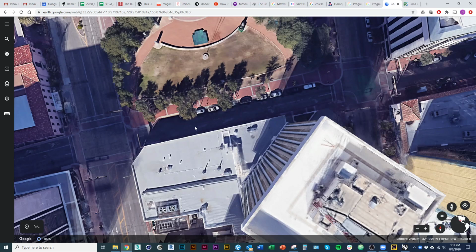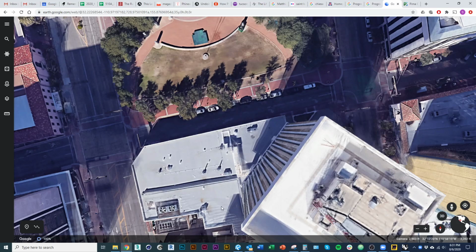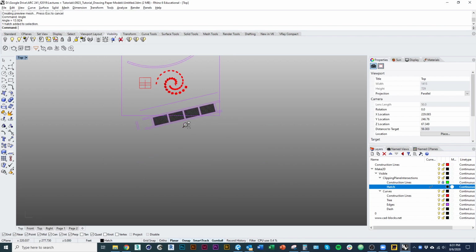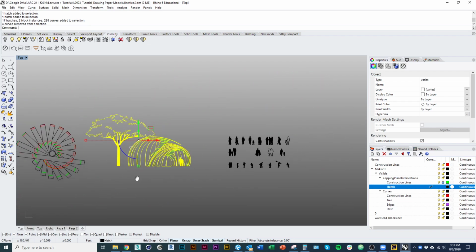But anyway, if I hover my cursor over the height of the street right here, we're at 2,368 feet. And if I hover it above the building, so if I go 392 minus 368, that's the height of my building, 24 feet. So in my plan here, or sorry, in my section here, and this is something that, again, I would just draw. I wouldn't bother trying to make a model.